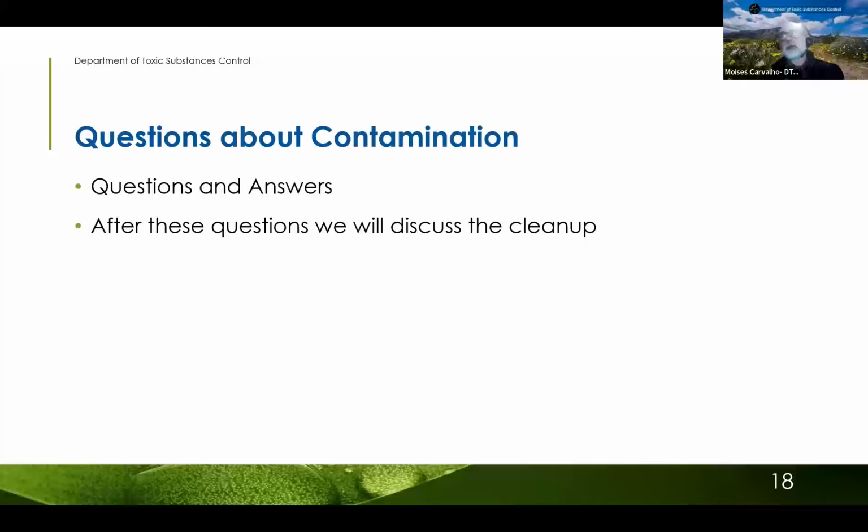Right now, some of the community members that live near the site might be seeing us doing some investigation on 31st and 30th Street. With this investigation, we're collecting soil gas samples to find out how far the contamination has spread as soil gas. Also, in a later stage, when we get those data, we're going to assess and make the correlation with the information we have on site. We also might install additional groundwater monitoring wells to understand how far the groundwater contamination has spread from the site.